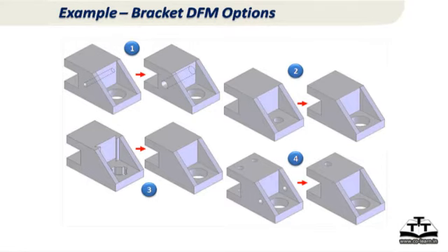Please remember that. And a few more examples of change. You can quickly look at the changes visually. First pair, the hole diameter is increased. Second pair, also the hole diameter is increased, because a thin hole in a thick section is bad. Third example, on the left side bottom, you are making a more complicated hole into a simplified hole. That reduces the core cost. And the fourth one, too many core holes, reduce the number of core holes, maybe drill them later.